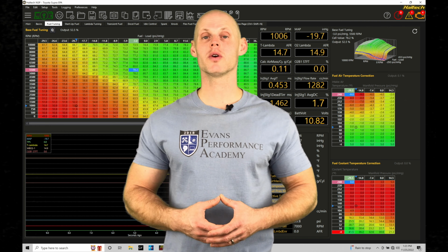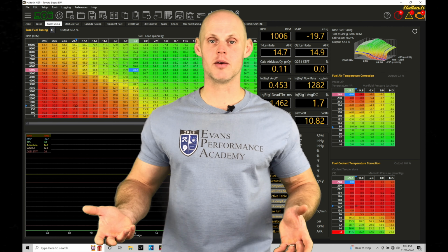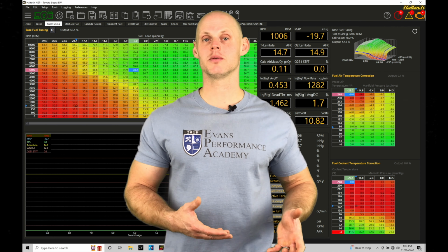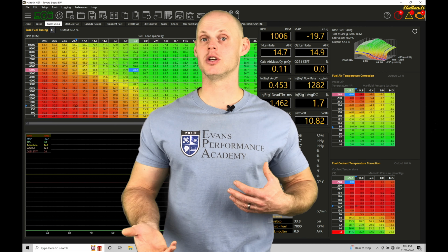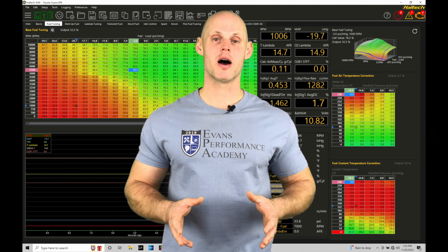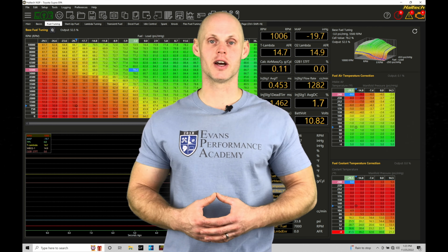In this training tutorial, we're going to be exploring using alternate load inputs for things like our speed density table. So how we can change out something like manifold pressure to something like throttle position or engine pressure ratio. There's a lot of options. We're going to talk about how all of these work within this training module. Without further wait, let's jump in so we can check this out.